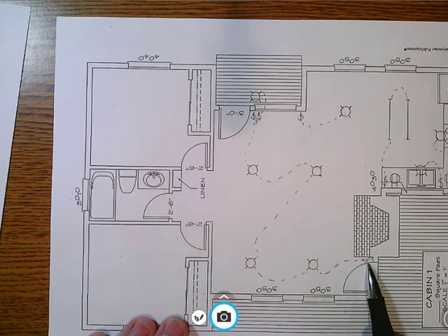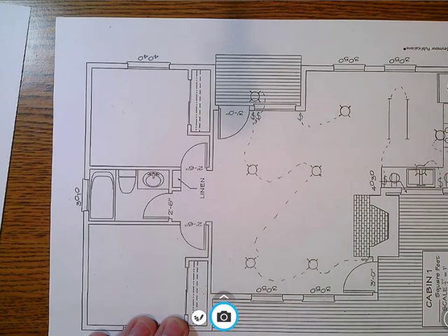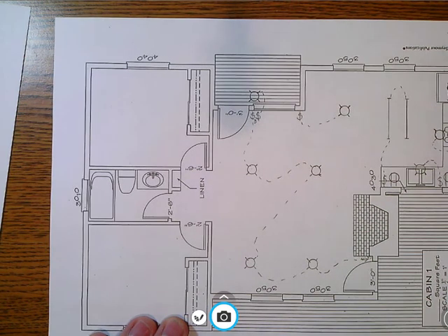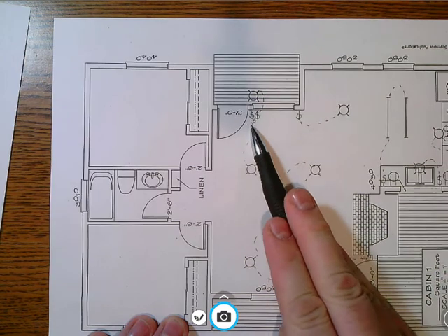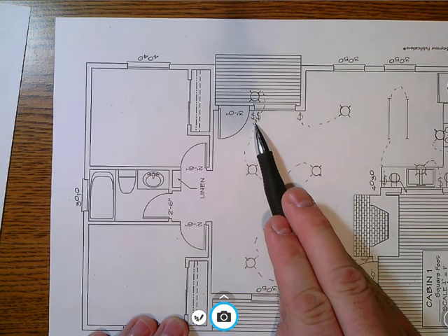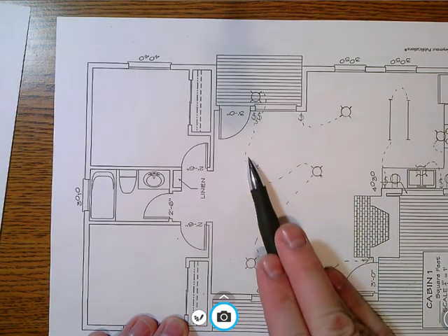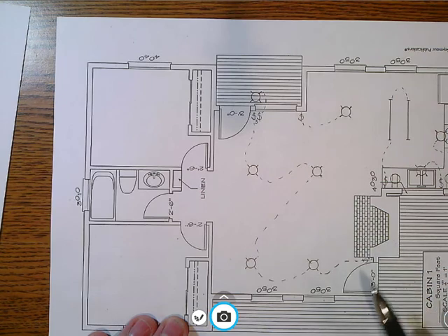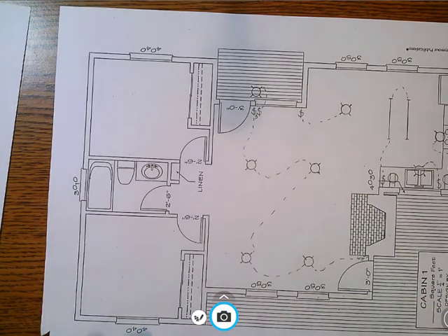All right, whenever you're doing a 3-way switch, when you have 2 switches going to one set of lights, you have to use an S with a subscript 3 next to it, because it lets the electrician know he needs to use 3-way switches and get 3-wire electrical lines to connect to these lights. So something to just keep in mind.